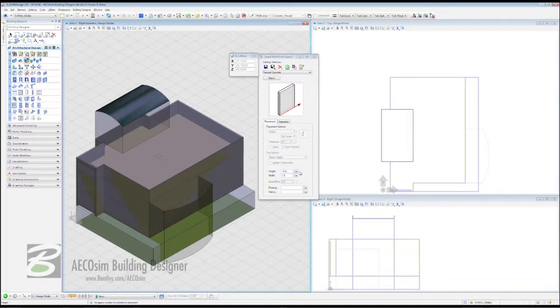And finally, our ground floor, we're going to change the material because we're going to zoom in here and choose brick. And again, let's use our history just very quickly. 16 foot, just in case anything changes. 1 foot for the thickness. Come in here, highlight the space. Click inside and once more to set. And our walls have been set.